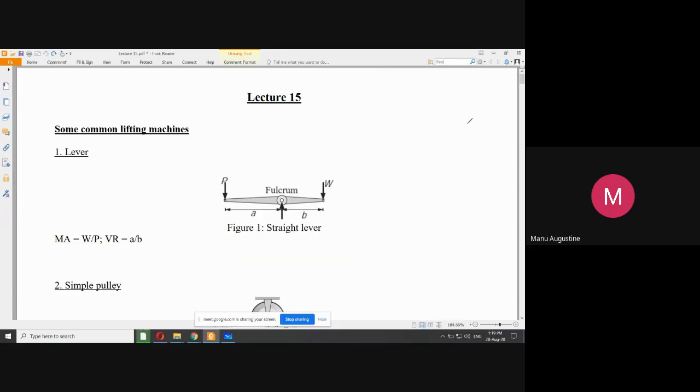So anyway, about the fulcrum, if I take the moment of this load W, then the moment will be equal to W multiplied by perpendicular distance B. So W into B is the moment about fulcrum of load W. And what is the direction of rotation of this moment? If you apply the rocket analogy that I taught you earlier, then this has a tendency to rotate in this direction, that is clockwise. So I will put a clockwise symbol for the moment of WB.